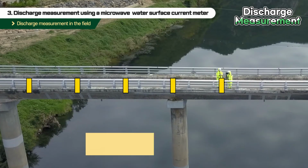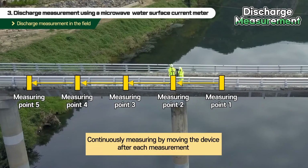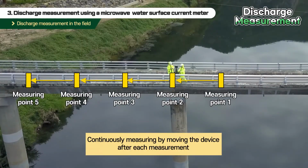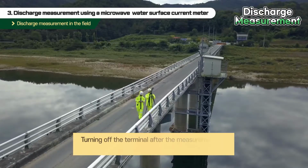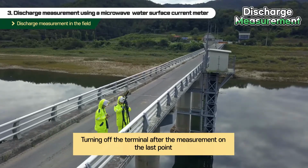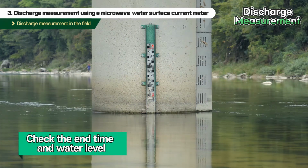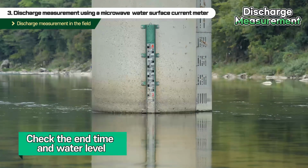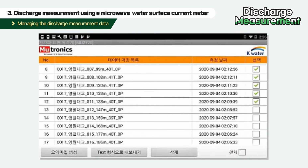After one measurement, move and install the device along the measuring points indicated on the bridge, and click the Measurement button of the terminal to measure continuously. Please turn off the terminal by clicking the button after completing the measurements at the last point. And then, please check and record the end time of the measurement and the water level. For the saved measurement results, press the Data View button on the measurement screen of the terminal. You can see the results here.